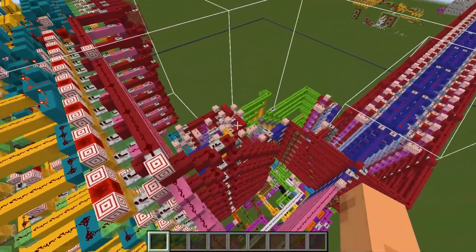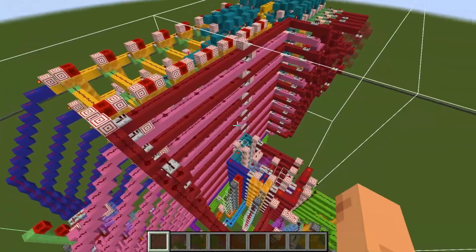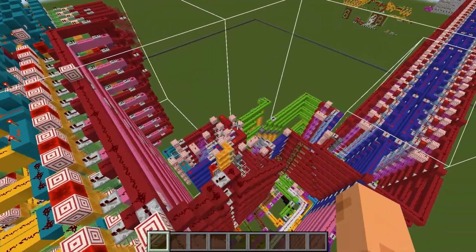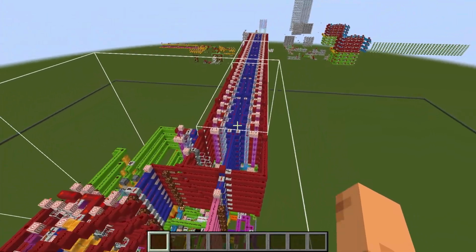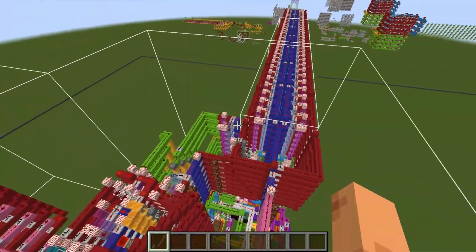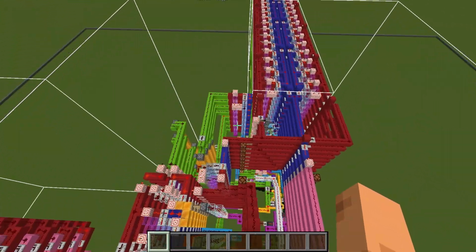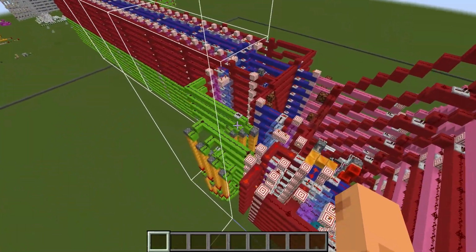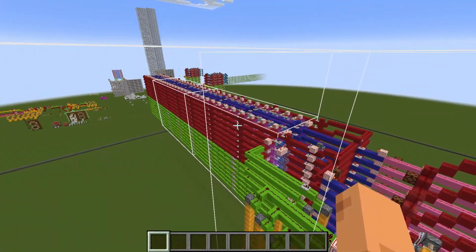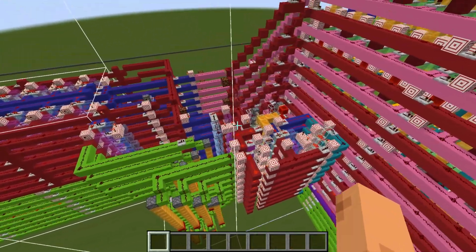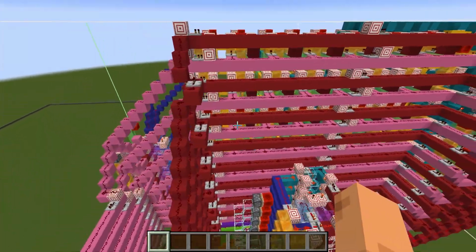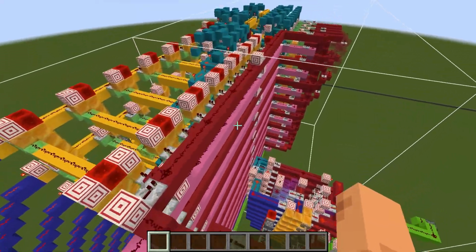One of them is the accumulator, which is the register that stores your working data value. And your second value usually comes from memory. So we have a direct wiring of whatever's being read from memory at the current address that becomes the second input into the ALU.